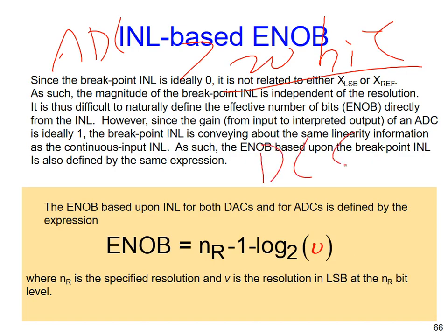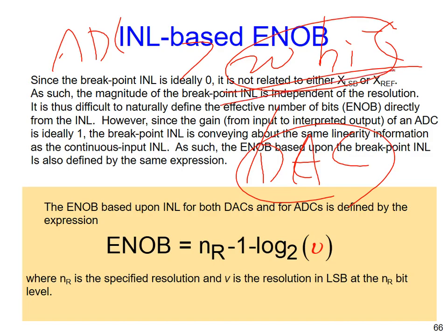The DAC itself needs to have inherent accuracy, 天生的精度, better than this. But I told you already, you have only a 1 bit or 2 bit DAC in the design. How can you achieve such kind of accuracy? You have only 1 or 2 bits. How can you achieve inherent accuracy of more than 20? It doesn't make any sense, even to myself, right?